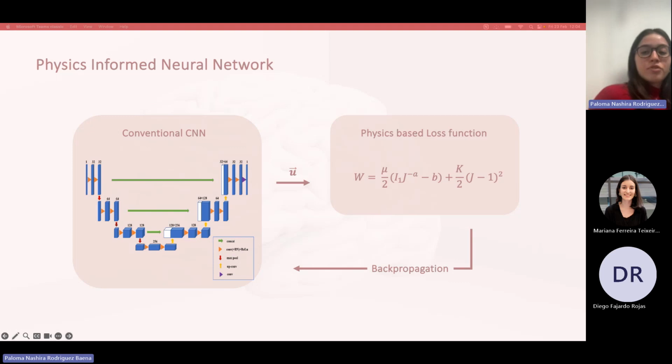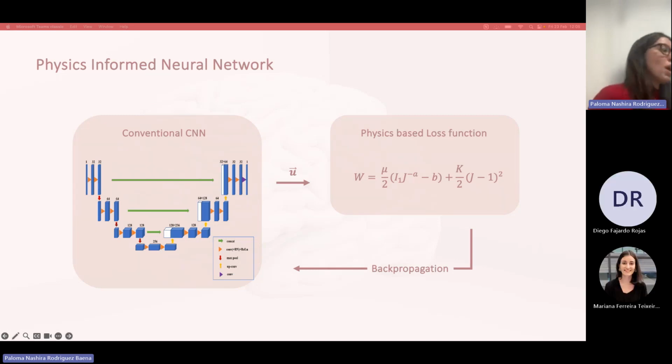the neural network block itself is flexible with its outputs, so it is technically free to violate any of these physical constraints. It would be the physics laws, a posteriori of the result of the network, that would be minimizing the violations according to the Neo-Hookean model. So even when using the Neo-Hookean model with a PINN, the Neo-Hookean model wouldn't be imposed on the outputs. Really, it's just the network that's being encouraged to minimize these violations. So technically, the model would be free to violate these physical laws, again, when extrapolating to new examples.